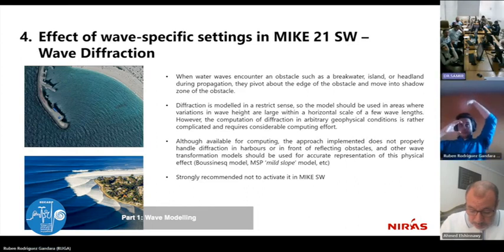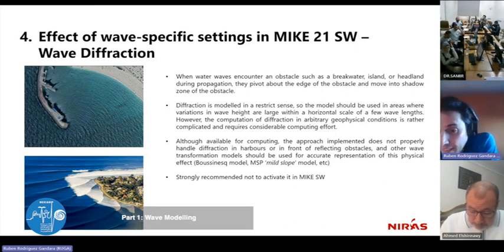So all the waves will hit in here, but at the lee side of the island you will have a very calm area, because those waves will travel around the island, will diffract a little bit, and will travel a little bit toward that calm area, but there will be very little energy, because the rest of the energy will keep traveling. But if you're interested in knowing what is happening in that area, you need to model that area specifically with another type of model, which can be a mild slope program, or a Boussinesq model.